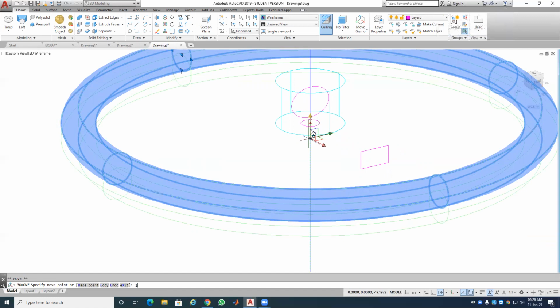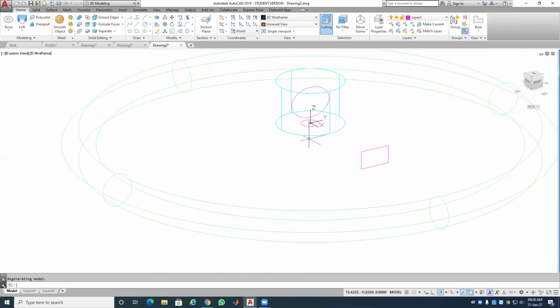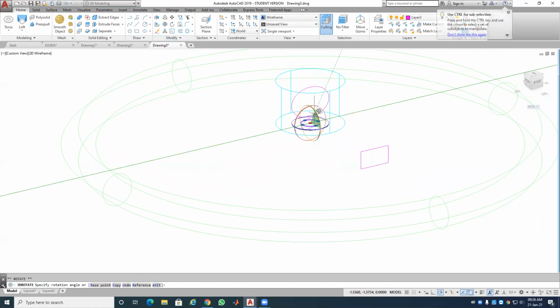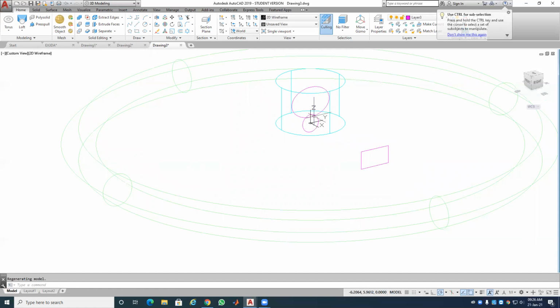By 10. And this one, I also rotate it using this 3D rotate 90 degrees. Then move this out 100 all the way to the torus, and move it down again by 10 so that it'll be inside the torus.